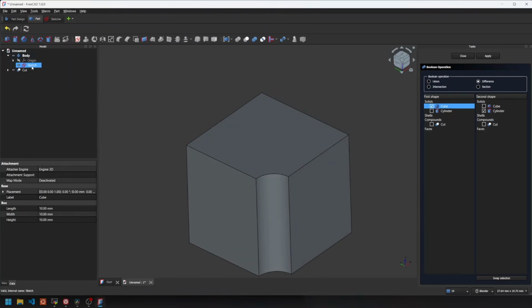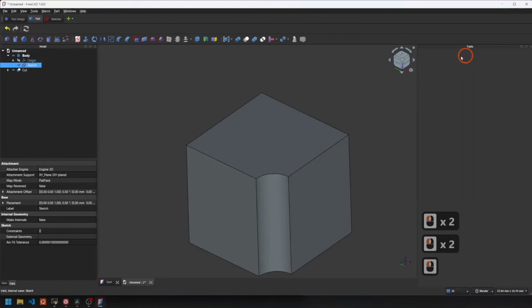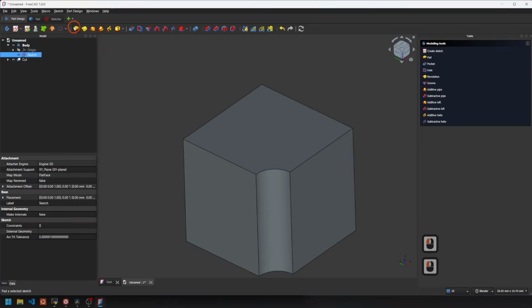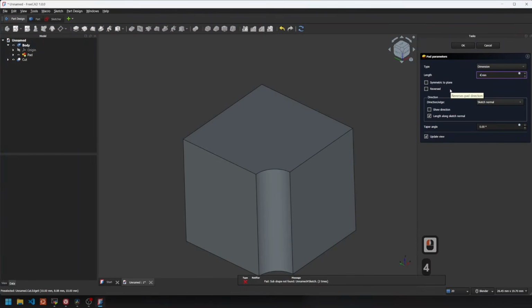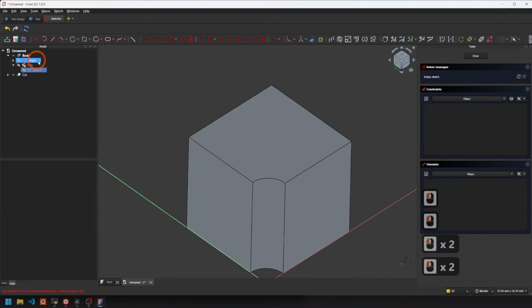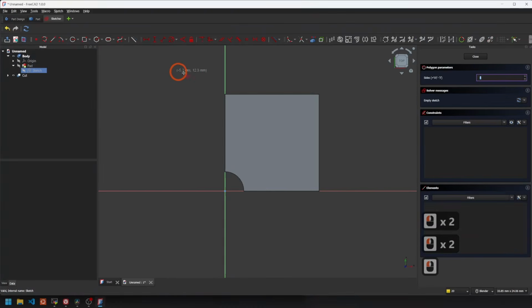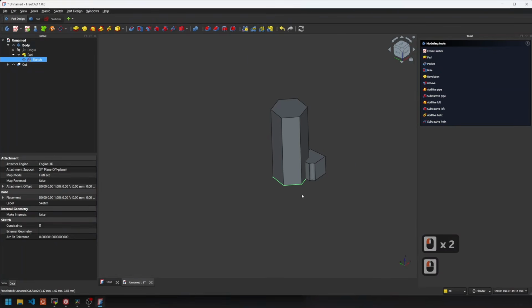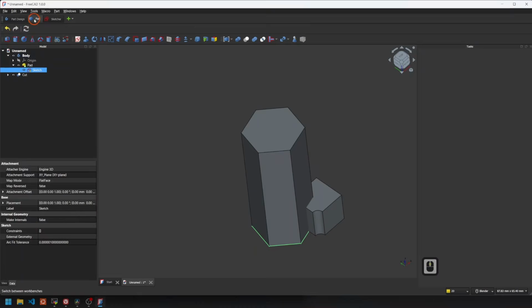Now, I can also do it with this body. Let's create a 3D object out of it first. Go back to the part designer, add some padding to it, 50 or 40 millimeter. Oh yeah, we haven't created a sketch here. So let's create a hexagon like this. And this should create it. Yeah. And then we go back to this part workbench.